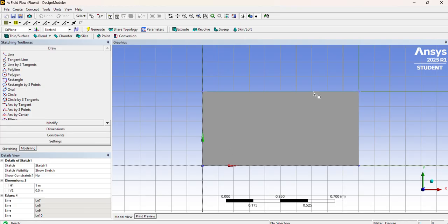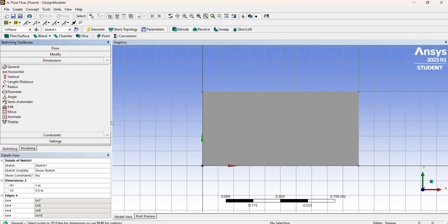So to start, you have to obviously make your plate. To make your plate, you go here, you use this rectangle tool, start at the origin, go out, just make things easier, and then you would have your plate. After that, you would want to make sure it's in the right dimensions, the horizontal being this side, vertical being this side. The vertical side doesn't matter an insane amount because you did not specify, but for the horizontal, you come here, you make it your height, which is 1 meter.